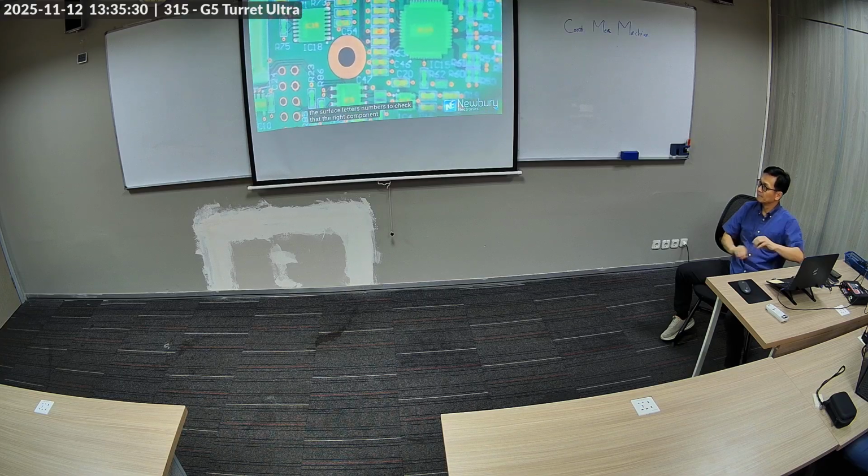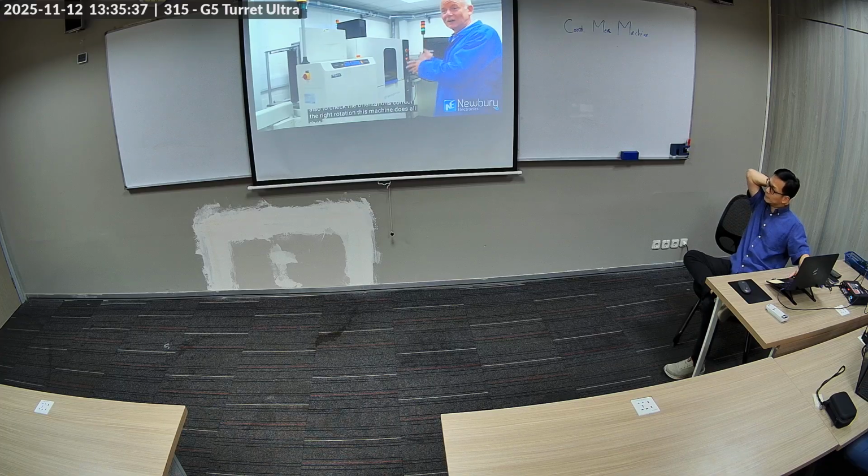Most AOI machines function by taking a digital image in 2 dimensions and comparing a good board with the board under test. They also do some image recognition to recognize characters on the surface, letters and numbers, to check that the right component is fitted and that the orientation, the rotation, is correct. This machine does all that, but in addition, it takes a measurement of the 3-dimensional state of the board, and it does this on a 20 micron mesh.